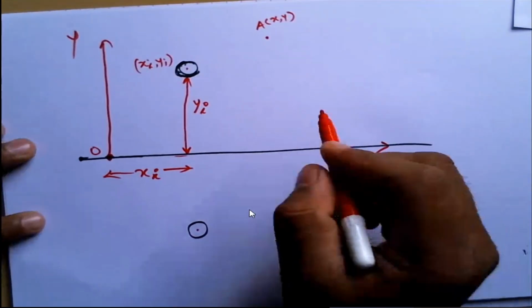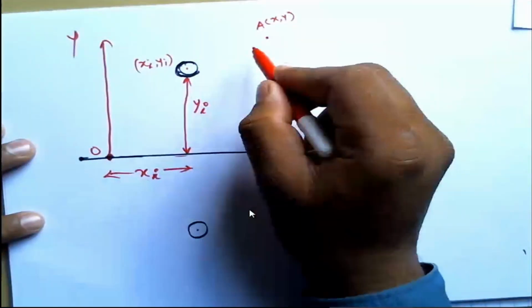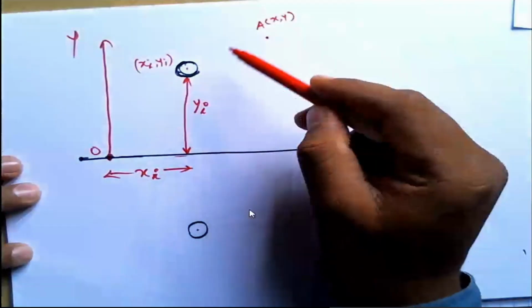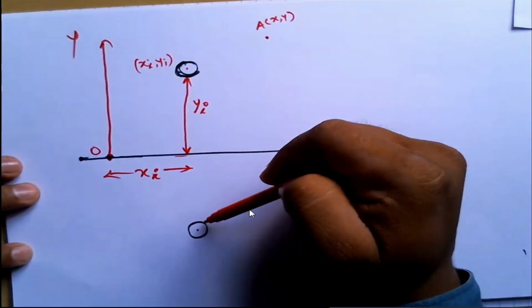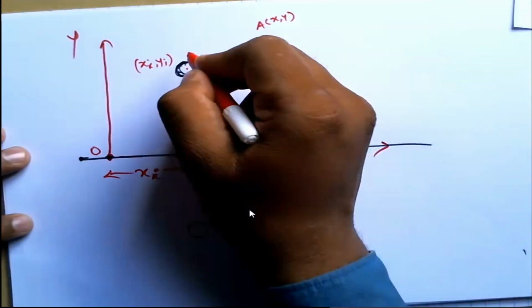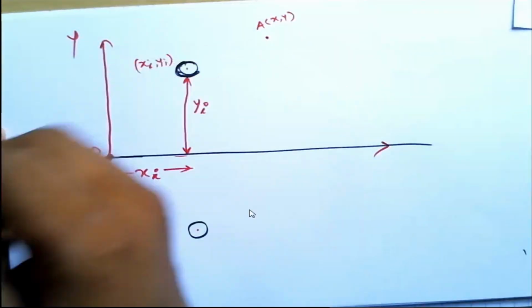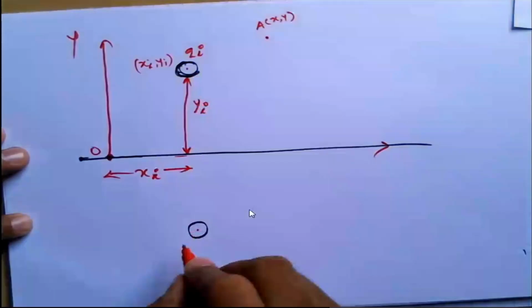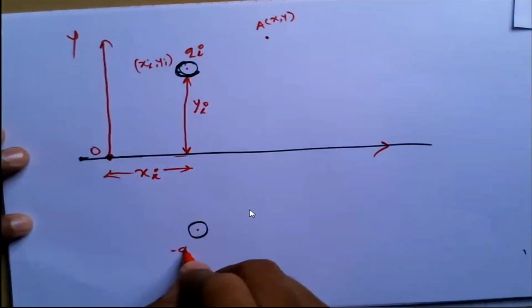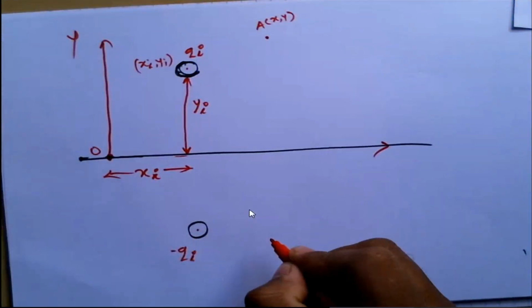Okay, so see, as this point it is in air, the electrostatic field at this point it is due to this conductor as well as this conductor. Okay, suppose this conductor is carrying charges qi, so image of this conductor will carry a charges of minus qi. बरोबर है ना?